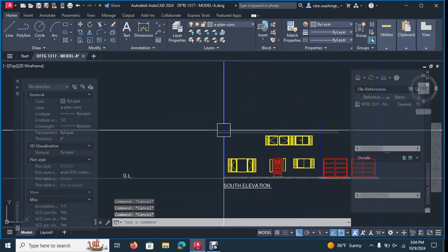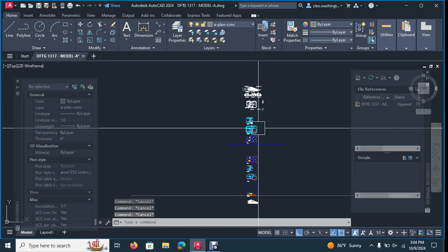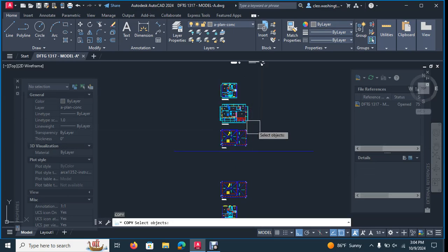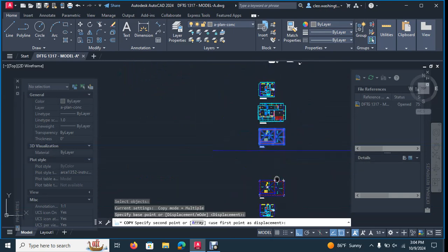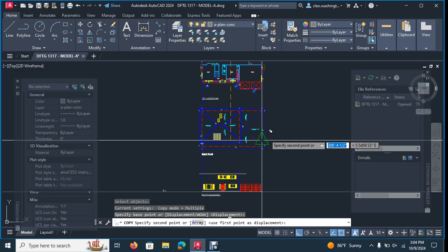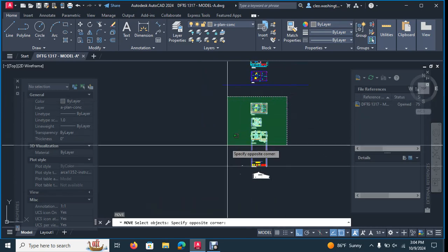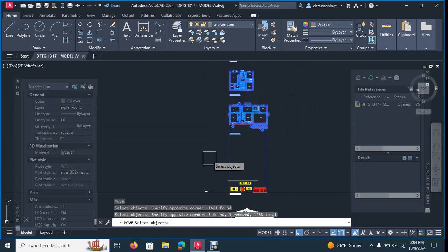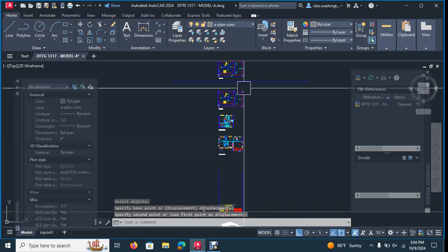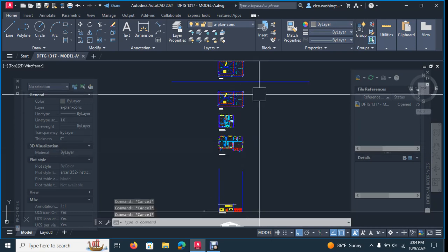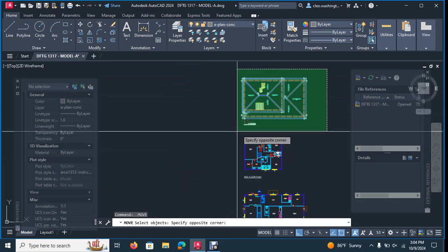When I say overhang, when you go back to the roof plan, in fact, let's copy the roof plan down because we're getting ready to project the roof lines down. So let's copy the roof plan down. Just leave it in alignment. In fact, let's move these up some because we don't need them. Unhighlight those. Let's move them up. And then let's copy or move this roof plan down.